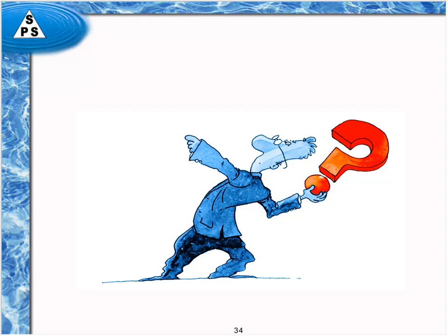Okay, we do have one chat question that has come in already, and actually came in during the middle of the presentation. And that is, it says, can we direct this toward medical devices? Well, yeah, we can. You know, a water system is a water system. And medical devices do require at least the use of a purified water system. Depending upon the medical device and whether it's implantable and whatnot, you may wish to use something akin to water for injection for the medical device if the level of endotoxin on the device or in the device might be a concern.